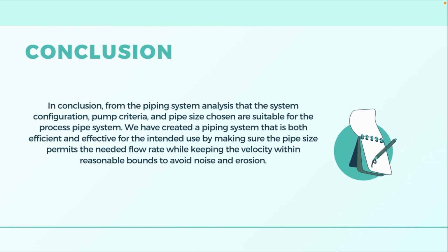using the head loss and Reynolds number. The friction factor of the larger diameter pipe is substantially higher than that of the smaller diameter pipe. The findings indicate that pipes, fittings, expansions, and contractions have an impact on the head loss. Furthermore, the velocity inside the pipe obtained is 3 meters per second. The value of head loss obtained is 21 meter.